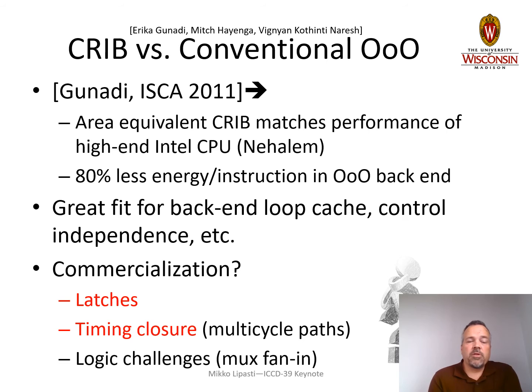There have been some efforts to try to push this into a commercial product. We're running into the same kinds of complaints and problems that we seem to run into a lot of the time: oh, our design flow doesn't support latches. You require latches in your design. Well, we actually have a way to get around that. How do we get to timing closure? You have multi-cycle delay paths here. Our tools don't support multi-cycle paths. Every latch to latch or flip-flop to flip-flop path has to be a single cycle. Otherwise, our timing closure just doesn't work.